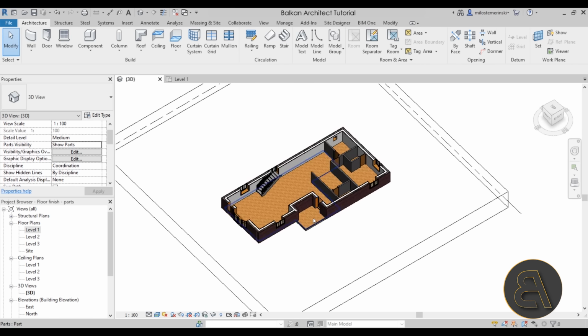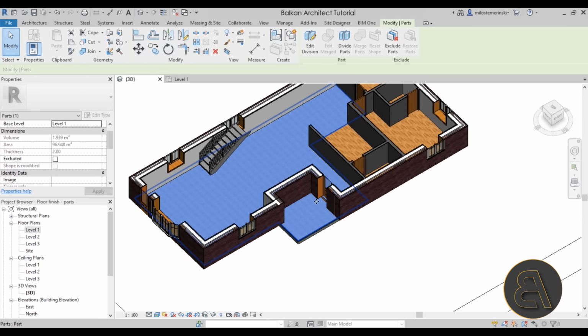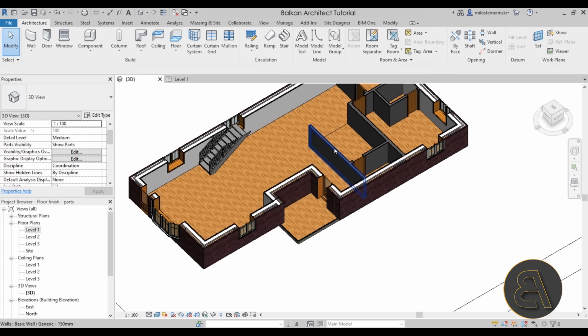So let's go back here into the 3D view, select the, see, okay, there we go. So for example, for this material, what we can do is we can go here and play around with this particular material. As you can see here, the properties panel includes some parameters, and for example, one of those is material by original. Now in this case, that's going to use the oak flooring. What we can do, of course, is uncheck that and then change the material.